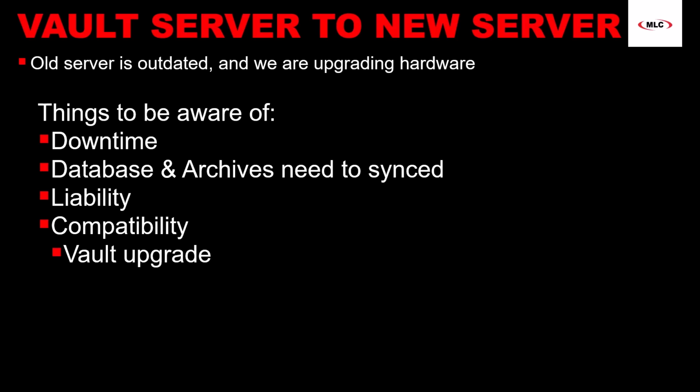They say, Roland, we bought a new server, it's got a new Windows operating system, it's got a new version of SQL, everything is good, but their old server is so far out of date that the old vault is not compatible with the new operating system. And in that case, it triggers them to not only need a migration, but also have to upgrade their current vaulting tool, meaning upgrading it from, say, PDM 2020 to, say, PDM 2025. So these are all things that we always want to be aware of and keep at the top of our head anytime that we're investigating the act of doing a migration.